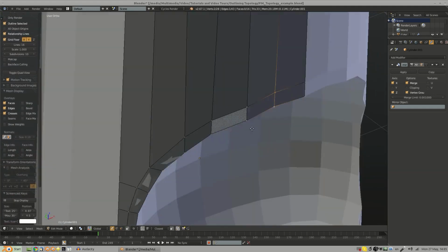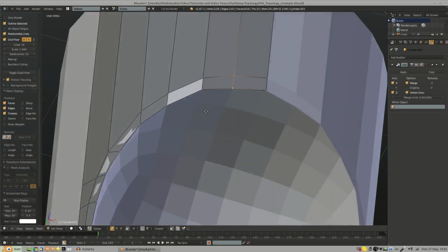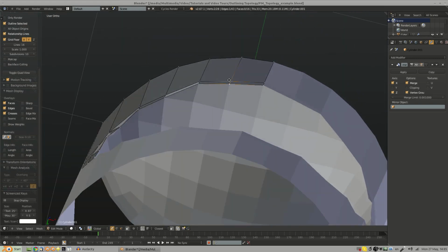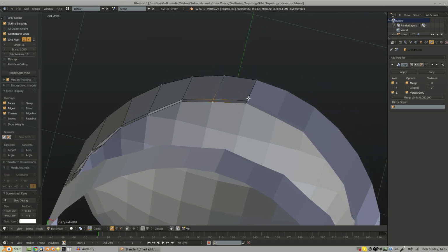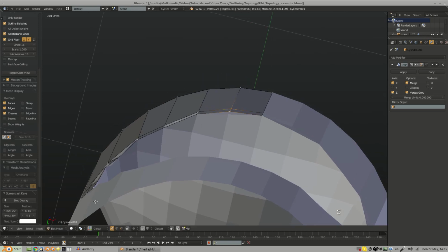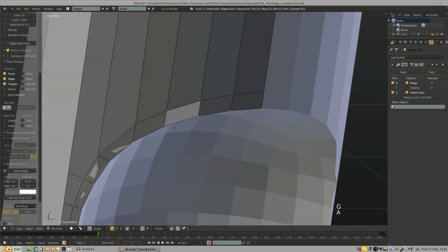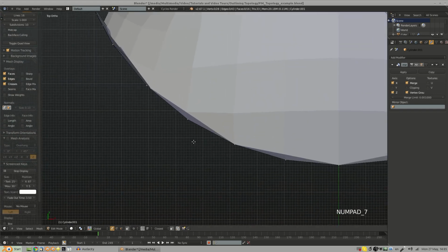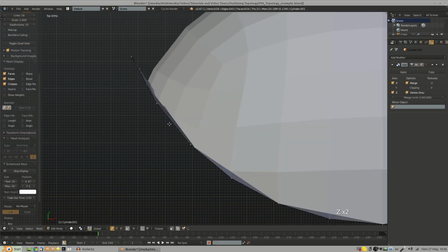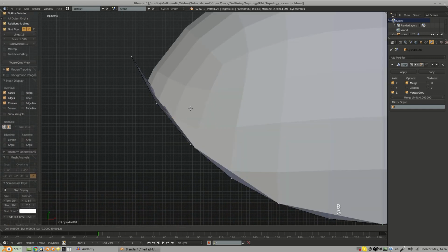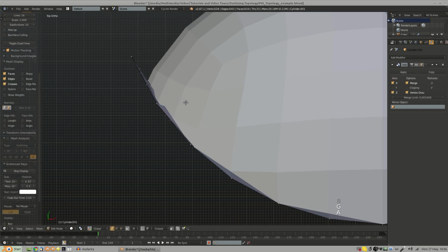So of course we can now see that I forgot to do something earlier, and that's to line these edges up with these ones up here. So we've still got this nice flat thing going on here. So I'll just move these around, lock the z-axis, and just snap it to those. And at the top here I can see that I'm going to have a bit of trouble with these vertices. I'll turn this back off. So I'm just going to move these around a bit.